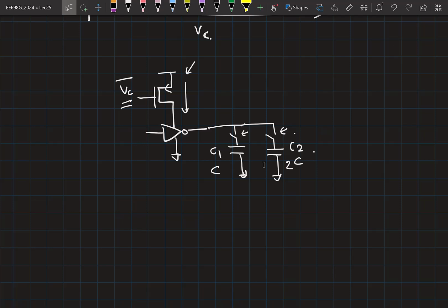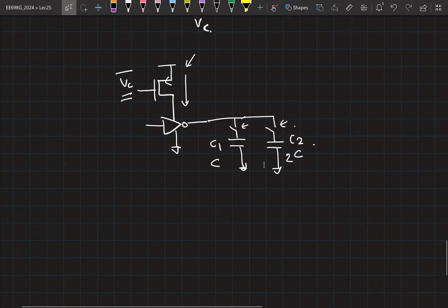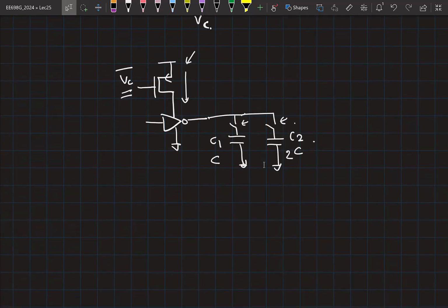This circuit will deploy after we got the larger units like 22.6 to smaller like 1.9. So your question is, if I were designing a VCO, do I start with a ring oscillator and then move to a VCO architecture? Right. If your aim was to design a VCO in the first place, you would start with a VCO architecture, not with a ring oscillator architecture without tuning ability. But you would make similar assumptions.